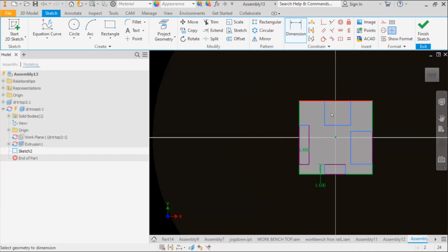And I think we're about to run into a little problem over here. And indeed we are. What happened is when I was drawing this, I got a slight little dotted line that connected from here to here. What that's saying is that's using a snap. It's causing this rectangle to constrain itself to this, and that's not really what we want. But I'm going to press on and not restart my video like I'm tempted to do. I'm going to click OK. I'm going to select everything on this sketch just like that. I'm going to right click and I'm going to delete it.